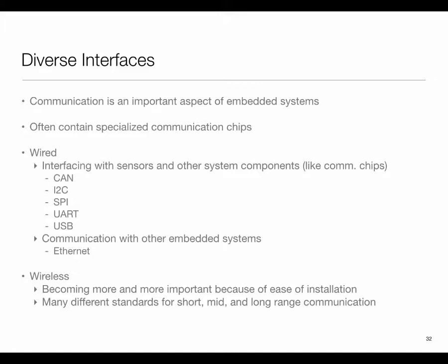It's a serial bus with multiple master capabilities. SPI, serial peripheral interface, is perhaps the simplest of the buses, just a pair of devices. UART is our good old serial stuff. Most UARTs can be operated in two modes, asynchronous and synchronous, and you'll see that in your embedded boards also. Asynchronous refers to the fact that the two sides do not have their clocks a priori synchronized, neither frequencies nor phases.